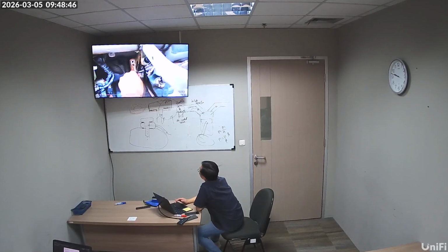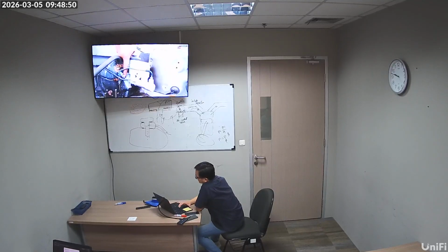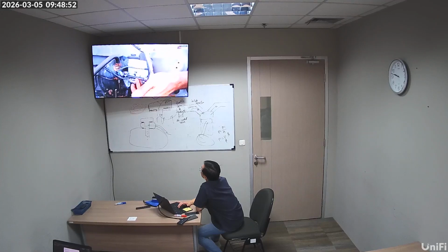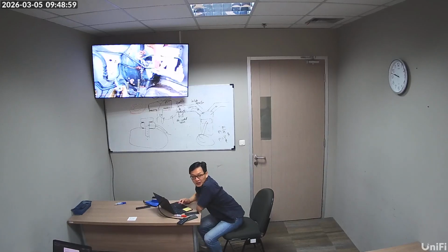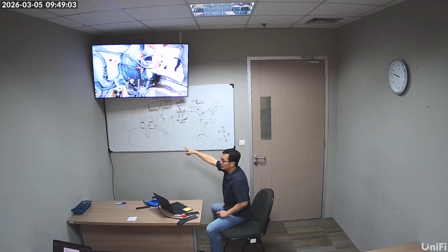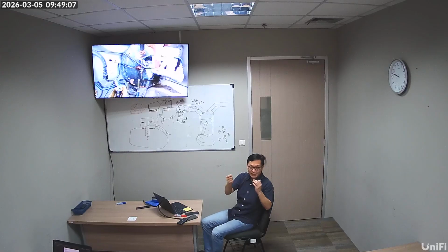That's just a bracket. There's a brake switch there. That's a brake line. Notice, by the way, the brake line is actually a rigid pipe. This is a rigid pipe. It only becomes a flexible hose near your caliper, then the pipe becomes a hose.